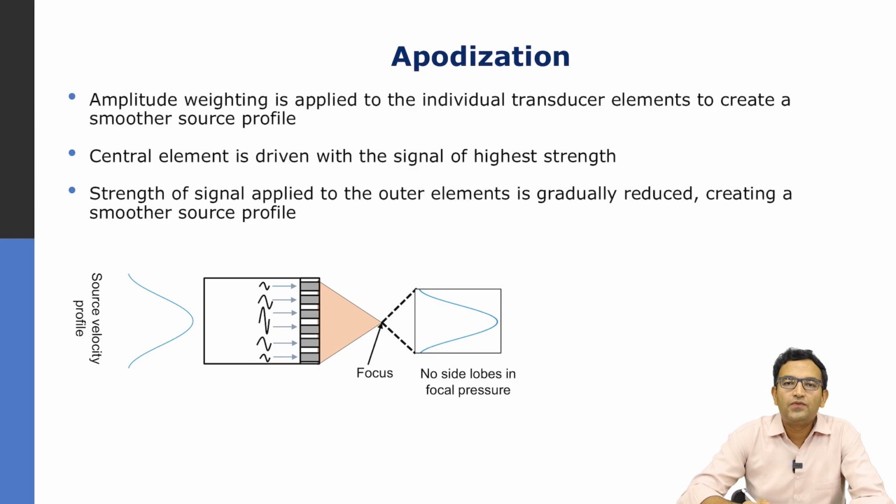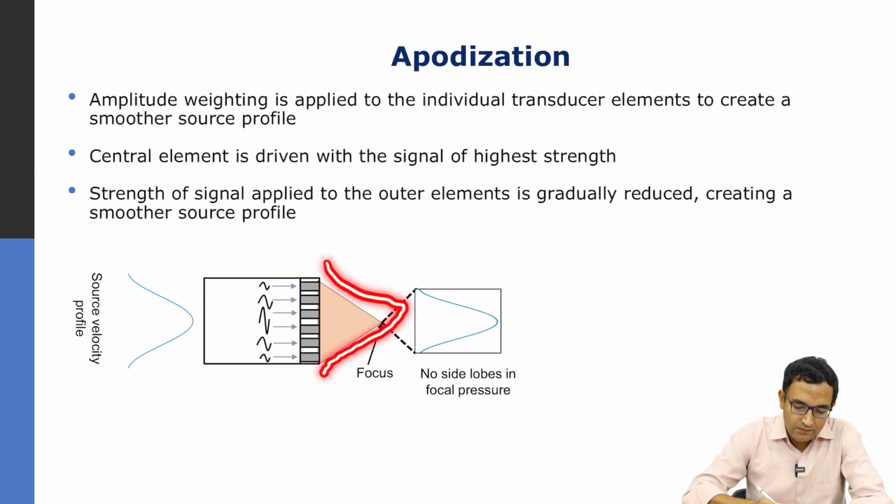If you remember, if you take the Fourier transform of a Gaussian function, the resulting Fourier transform also has a Gaussian profile. Now, it would be impossible to apply a Gaussian here because a Gaussian requires infinite support. If you truncate a Gaussian, it is not Gaussian anymore. The Gaussian function goes all the way to infinity on both sides, but this is a good analogy to understand that if you have a smooth profile and you take the Fourier transform, you will again get a smooth profile and the side lobes will be reduced.